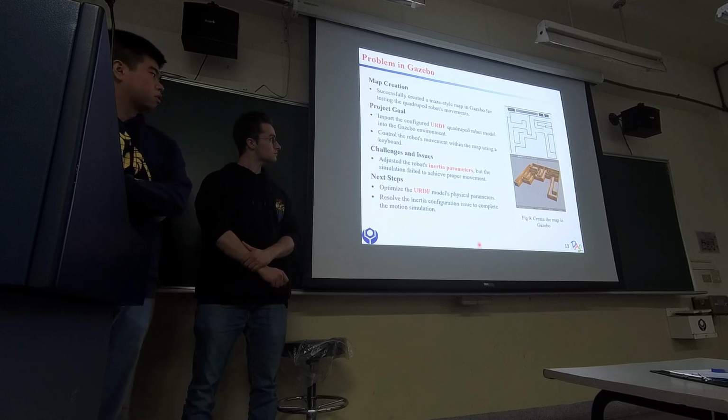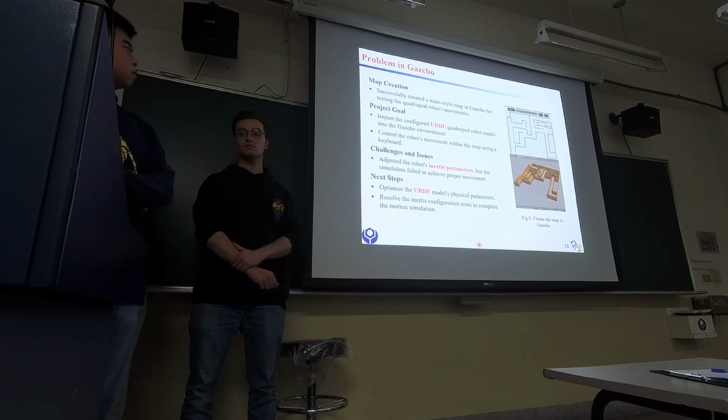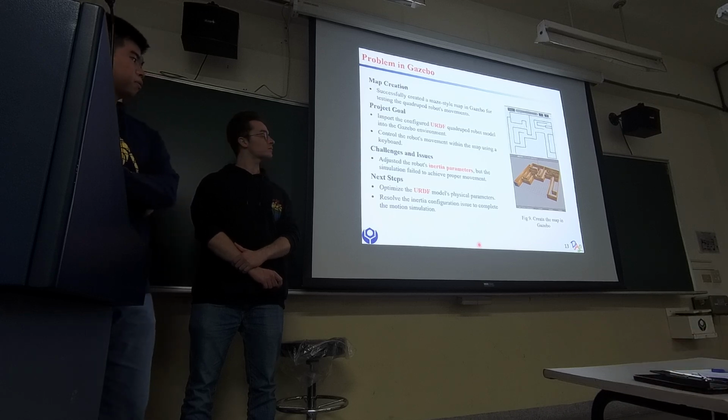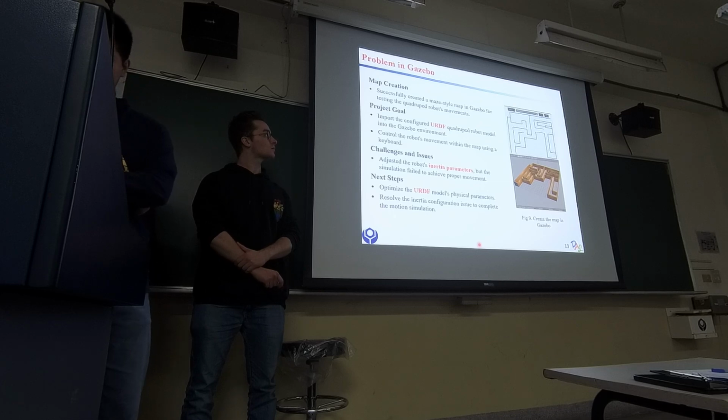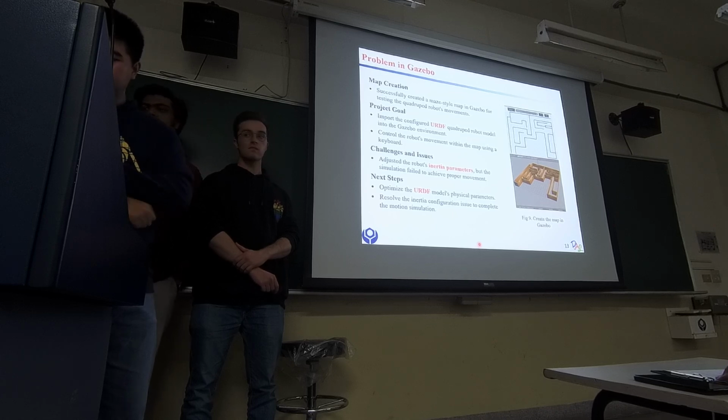Next steps. First, optimize the URDF model's physical parameters. Ensure the inertial matrix is correctly computed and matches the robot's physical characteristics. Second, restore the inertial configuration to fully complete the robot motion simulation in Gazebo.